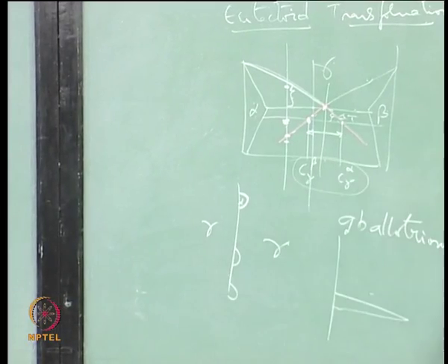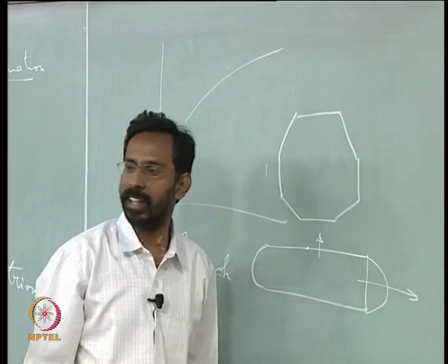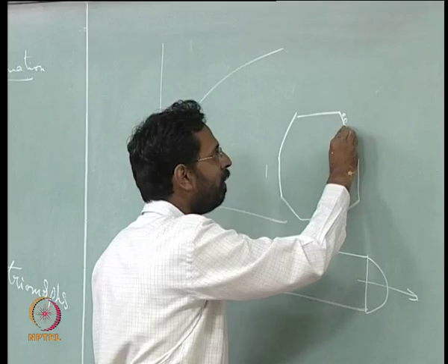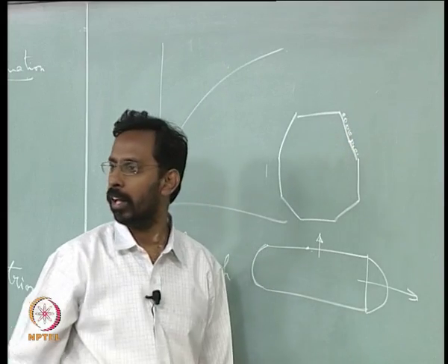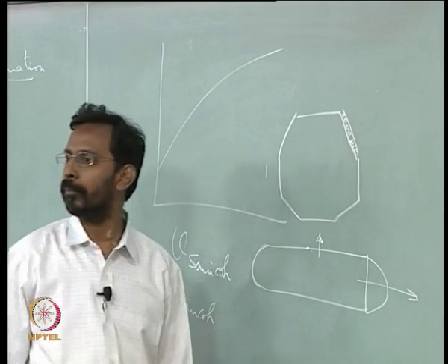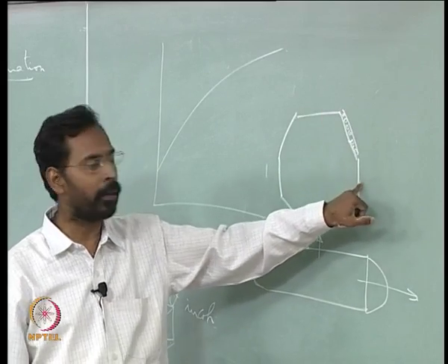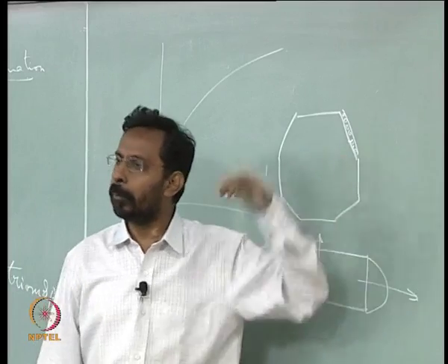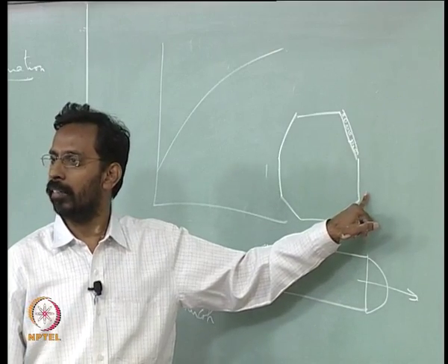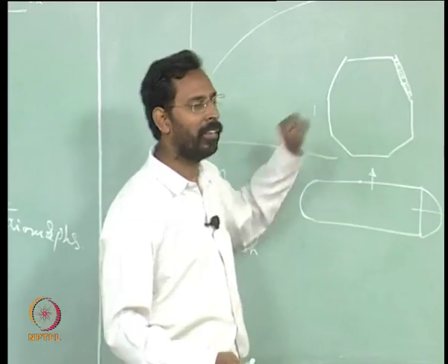If you have planes like this, something like this, let us say this plane needs fewer atoms to grow. Once all the necessary atoms come and join within a particular unit area, it grows by a small delta x, which is maybe one monolayer. Similarly, within that particular time, if the number of atoms required for this other plane to get completely filled have not reached, then this will not grow, isn't it? So like that you will see the growth morphology will sometimes be entirely different from the nucleus morphology.